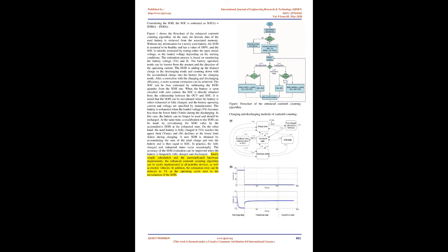However, the releasable charge is always less than the stored charge in the charging and discharging cycle. In other words, there are losses during charging and discharging. These losses, in addition with the self-discharging, cause accumulating errors. For more precise SOC estimation, these factors should be taken into account. In addition, the SOC should be recalibrated on a regular basis and the declination of the releasable capacity should be considered for more precise estimation.